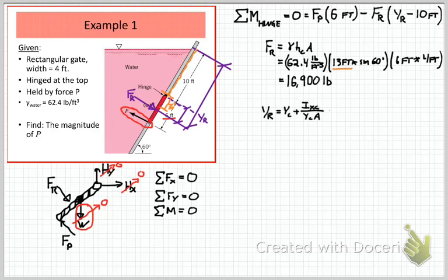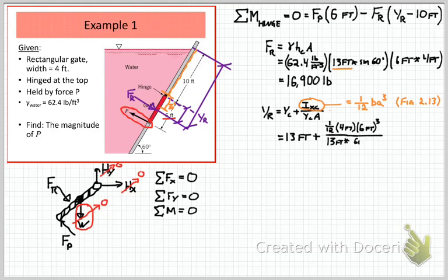Where that force is acting, it's acting at the center, a distance from the water surface plus the moment of inertia divided by the centroid times the area. This equation we look up in the textbook, and because we're always adding some moment of inertia, in this case for a rectangle shown in the orange type here, that YR is always going to be lower than YC.